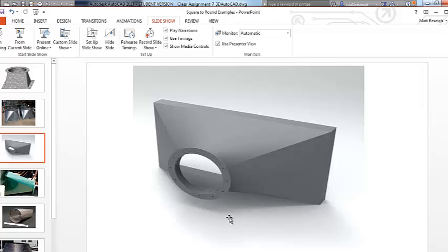So here's more of a pan. We think of squared arounds as duct or whatever, but it can be a big catch pan under equipment. All kinds of uses for something like this. It's a catch pan, and this is definitely a rectangular round, and it's actually even offset. So it looks to me like this one is not an equal taper. On the left of this picture, it's closer to the edge here than it is over here.